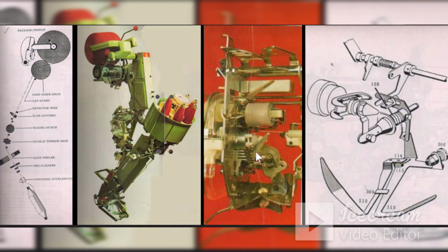This arm, that is one arm of the gate filler, is fixed. You can see the other arm can swing. What you notice here is that the two gates are away from each other. This gate filler remains open during winding. The moment yarn breaks and spindle stops, the movable arm of the gate filler moves towards the fixed arm.